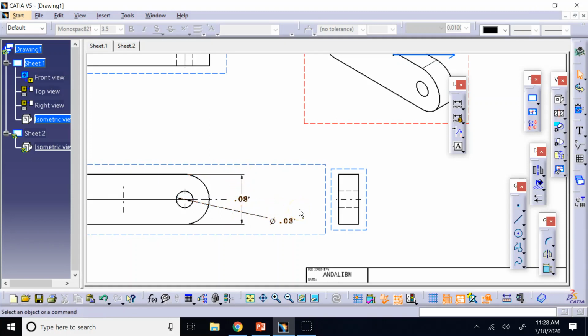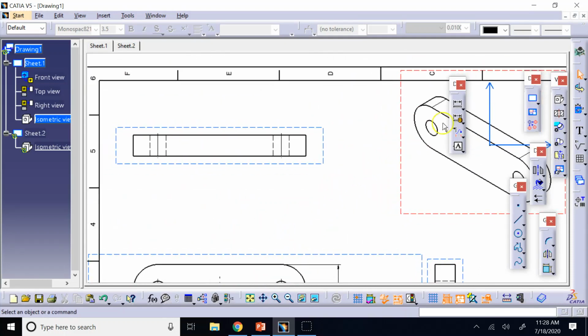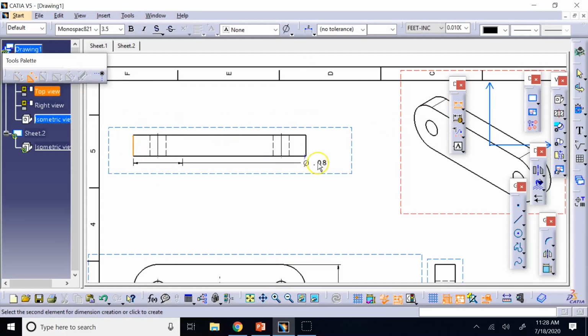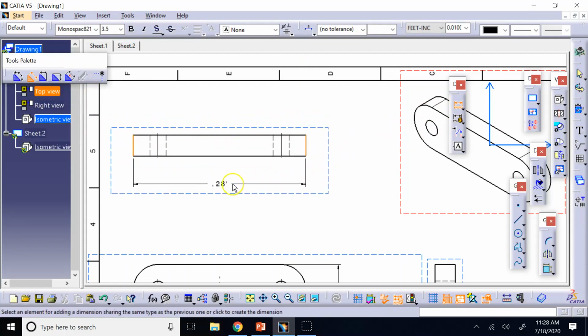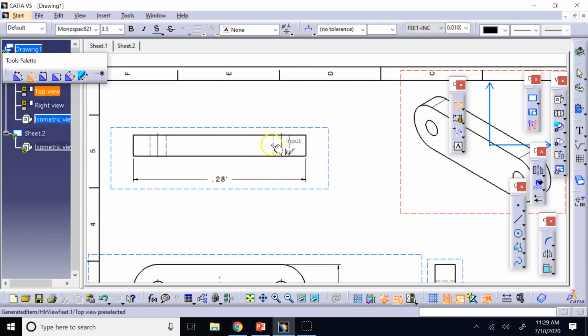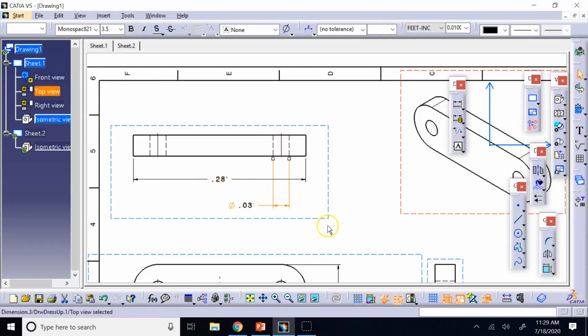Now sometimes a dimension line and an extension line might cross each other, okay? Try to avoid that as well if you can, but that's not a huge error. So let's say here I provide the length of the object, the width of the object, and then that's an error. Don't do this, but let's say I show the diameter here and I bring it further away. So I put the bigger dimensions closer, the smaller dimensions further away from the view. What happens here?